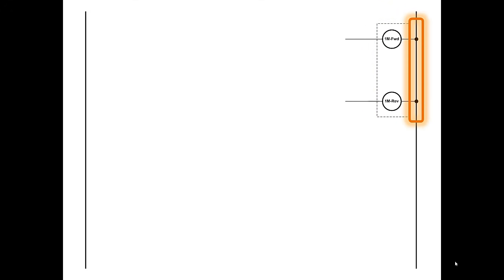It's really just one electric motor represented by 2 solenoid coils that control the switching of the direction. So we show several connections here. These 2 connections here are the common, but they are common to both directions of the motor. So really it represents one path of conduction, the common for the motor. We have a connection for forward and another one for reverse.